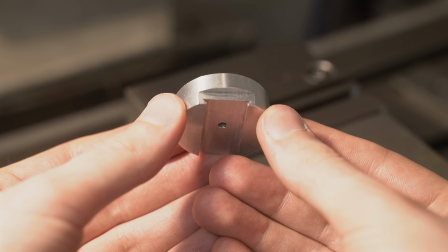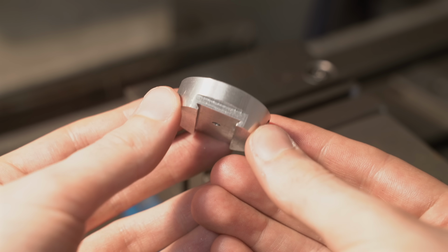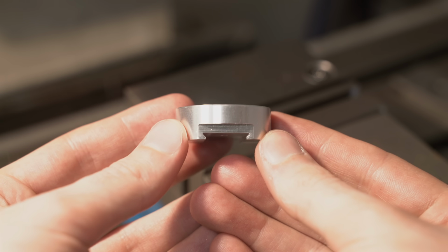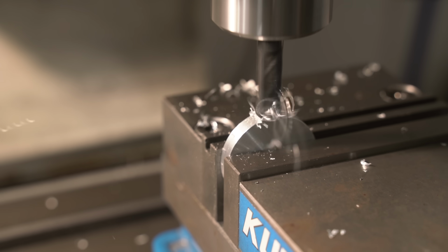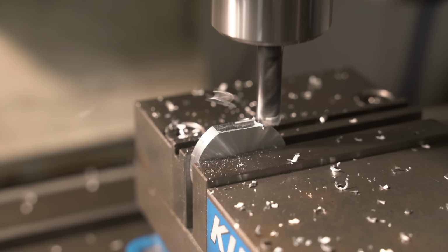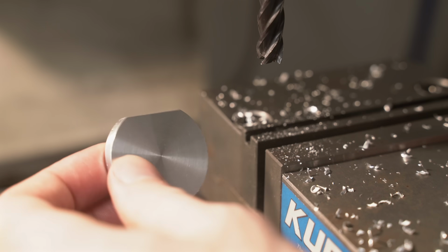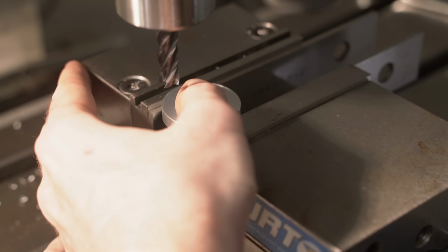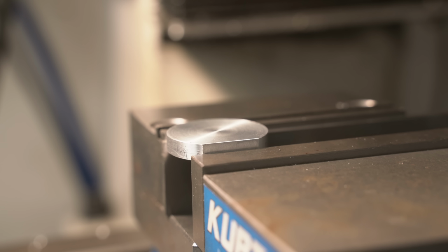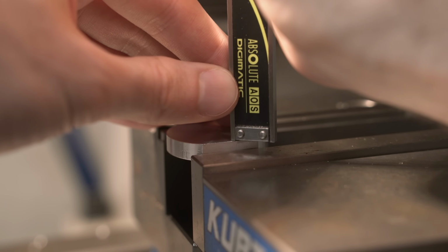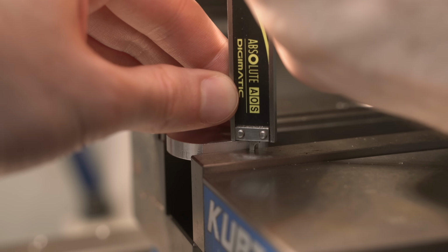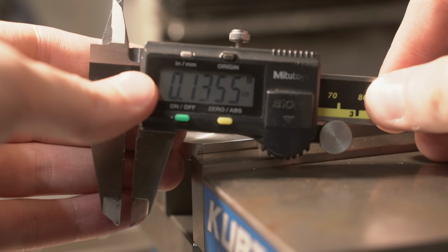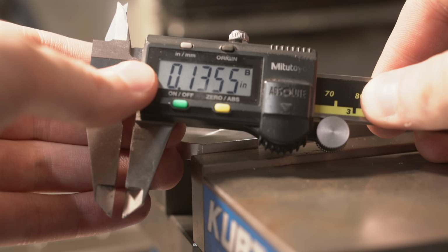As a reminder, I'm trying to replicate this dovetail slot here so that the disc can be mounted in the SEM. The first step of that is to cut a flat face to a specific depth on one side. This flat will also allow us to mount the disc horizontally in the vise. The slot for the dovetail is 1/10 of an inch deep, and I was worried that I might not clear the vise jaws. However, it looks like we just made it.